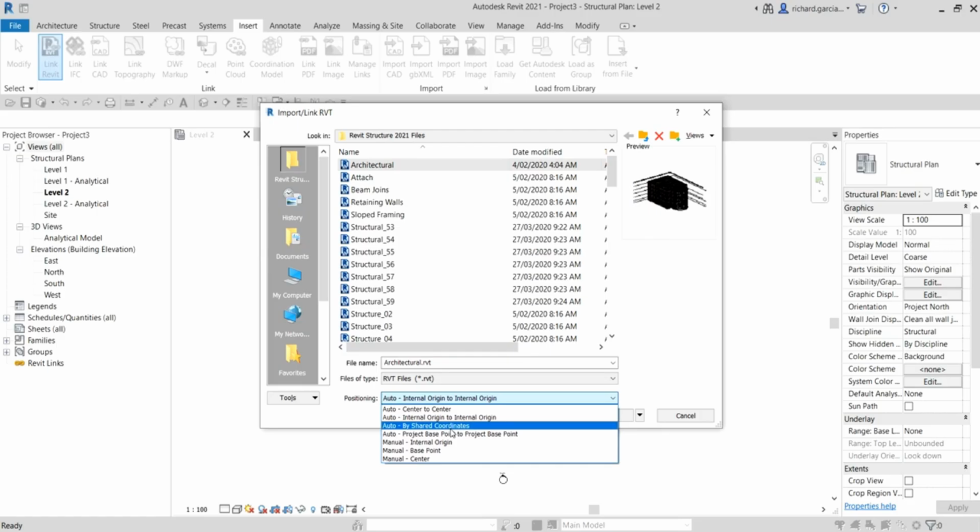Okay, so if you are linking a drawing file, you can use this positioning option, the shared coordinates option, to establish shared coordinates with the Revit model. If the incoming geometry is a CAD file and it does not share a coordinate system with the host model, the incoming geometry is placed by aligning its origin with the shared coordinates of the host file. Basically, when working with multiple links from different sources, coordinate a shared position with all members of the project team. This strategy provides the most reliable results for positioning models and ensures that the link geometry is aligned with the host model.